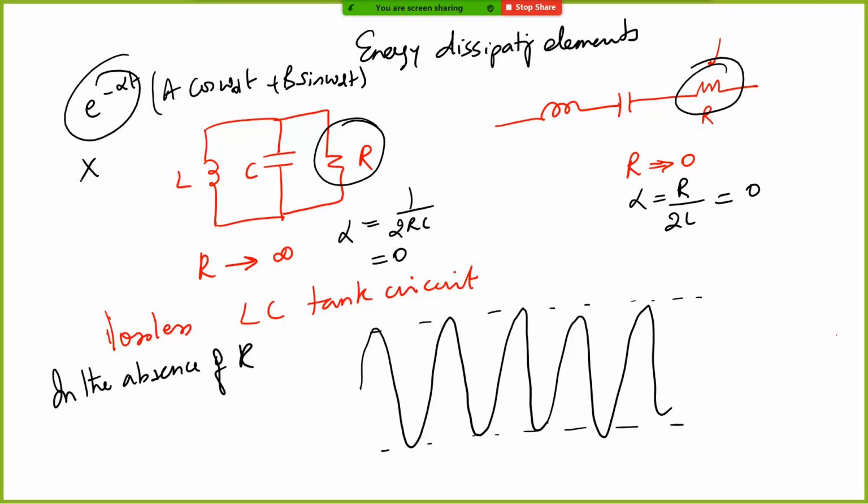All right. So the concept of an oscillator circuit, which we will see in analog electronics, is to somehow compensate for this loss in the LC circuit. If you can somehow provide energy to this LC tank circuit such that it compensates for the resistive dissipation, the energy dissipation in the resistor here, you end up with an oscillator, and that is the concept.